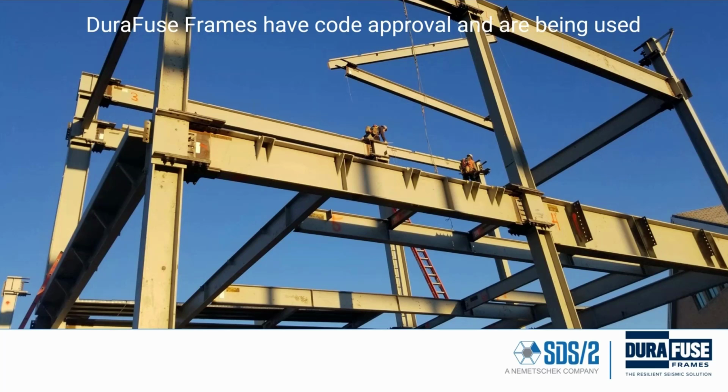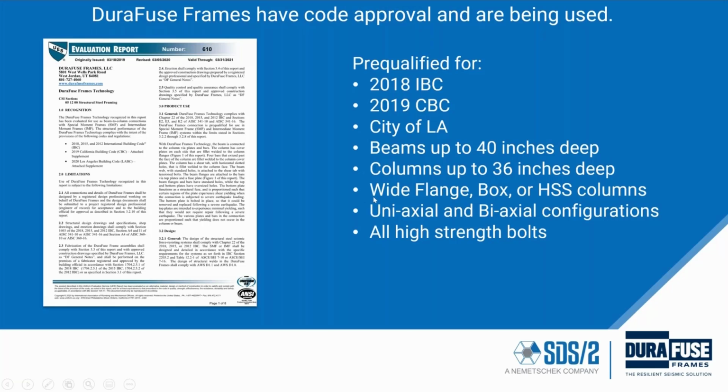Another reason people are using it is that DuraFuse frames are generally less expensive than other special moment frames, for a few reasons that I will mention in the remainder of these slides. But first, just to let you know, DuraFuse frames have had code approval for about a year. We've been used in several projects, and we have several others that are under construction right now, and a lot more coming down. So if you haven't detailed a DuraFuse job, you should in the near future.